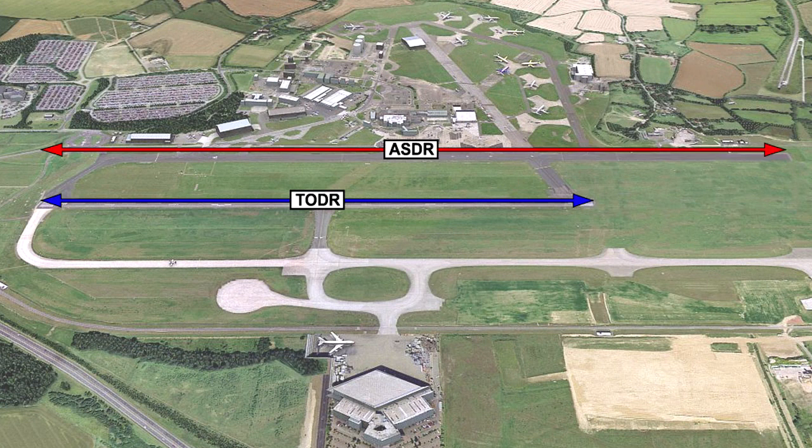If the anti-skid system doesn't work, then the stopping ability will be severely reduced and will cause the accelerate stop distance to increase dramatically. To solve the problem, V1 is reduced. You may recall that reducing V1 decreases the accelerate stop distance, but the side effect is that it increases the takeoff distance.